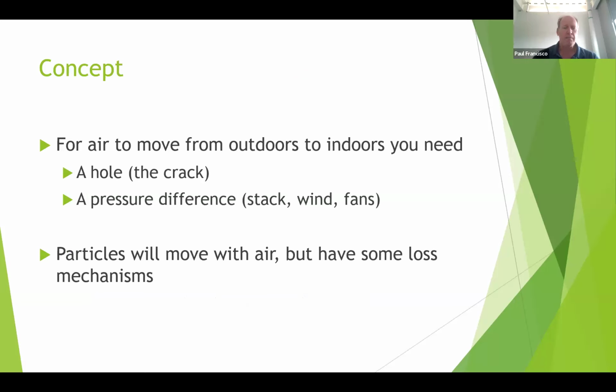At a really fundamental level, in order for stuff to go from outdoors to indoors, you need two things. You've got to have a hole, and that's the crack. You've got to have a pressure difference, which can come from stack or wind or fans. The stack and wind, that's a lot of what Tammy and Dom have been working on. But you can have a huge pressure difference, and if there are no holes, you're not getting anything going from outside to inside. And you can have huge holes, but if you don't have a pressure difference, you're not having anything go from outside to inside. So you really have to have both of these.